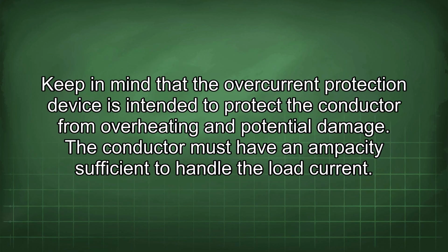Keep in mind that the overcurrent protection device is intended to protect the conductor from overheating and potential damage. The conductor must have an ampacity sufficient to handle the load current.